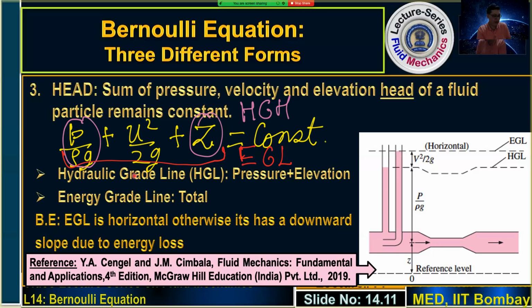So in this, what is shown is you have a piezometer as shown here, and you have a pitot tube. All of you know that with this piezometer, the fluid which is near the solid surface of the pipe has zero velocity. The pressure of the fluid which has zero velocity near the wall is measured here. This is called the static pressure. Now the pipe diameter is not large, so the elevation we can consider to be constant. So Z is almost constant here, and this corresponds to Z plus the static pressure.